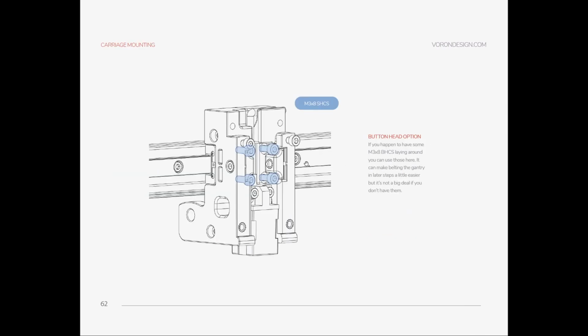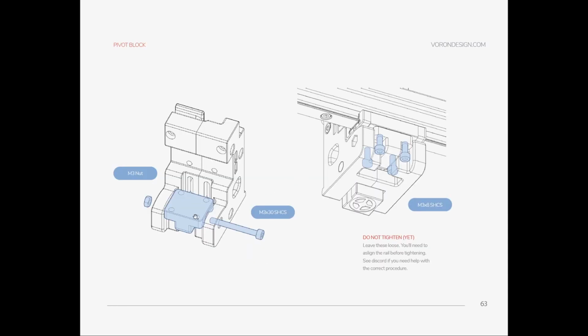So this front rail is the rail that you tighten and torque. For the second one, the bottom one, mount your head, and after that move your head left and right, hold the rail, and then put your head at the rightmost and try to torque the screws of the rails. Torque the first of them, move the head, torque the second of them, move the head to the other side, etc.